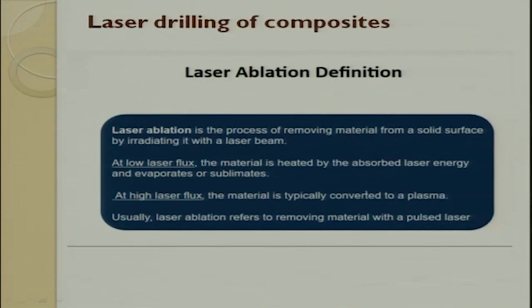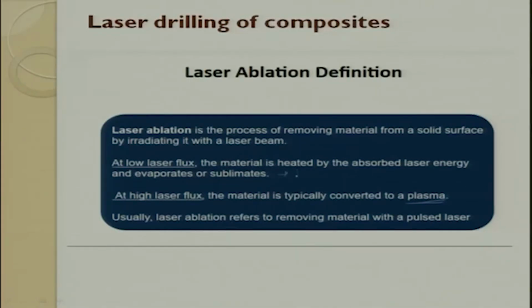See what happens when we try to remove polymer material using a laser. Plasma is also getting formed. The machining with laser has a big science behind it. There is recoil pressure and a plasma that comes in, but all those things are beyond the scope of this lecture. All we have to know is what I talked about as photolytic, and what I am talking about now is the pyrolytic. Pyrolytic means heat is applied for removal. Photolytic means there is no heat; the laser has a wavelength, this wavelength interacts with the bond and scissors the bond, and the polymer gets sublimated.